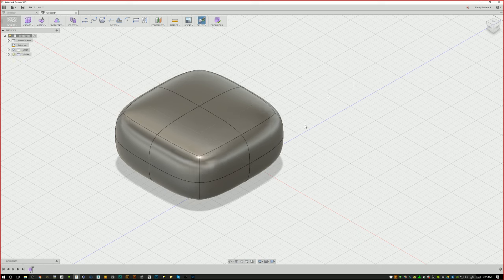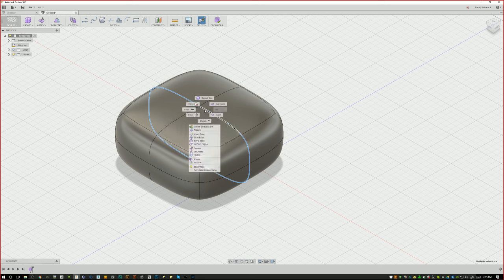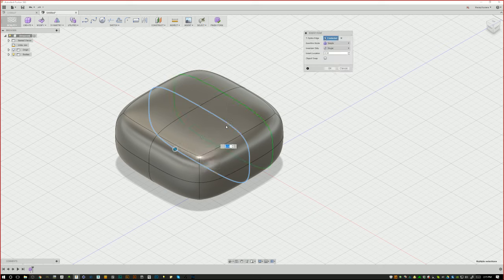Now if you actually try double clicking, so click on that center line that goes all the way around, right there, and right click. You can actually say insert edge. So now you can add more definition. If you drag that little bar, it'll add more of an edge. So try to bring it as close as possible to maybe the left edge, right there. Perfect.